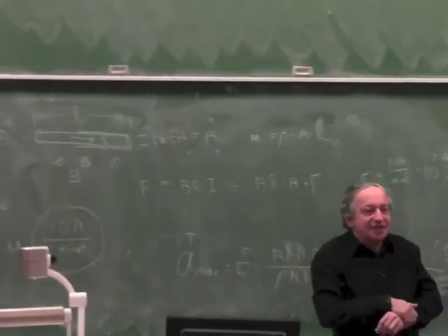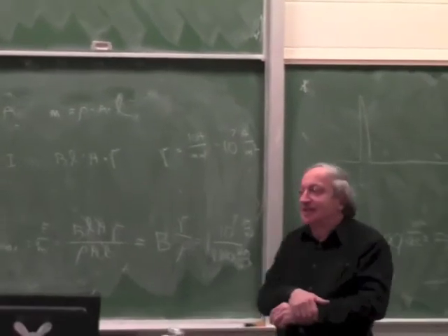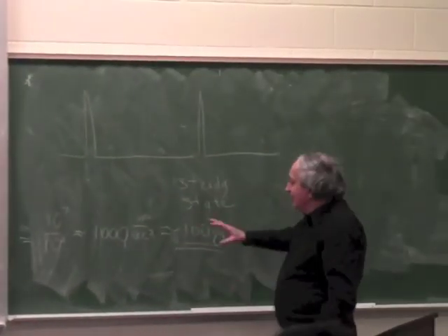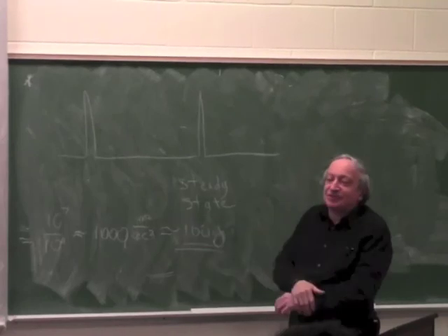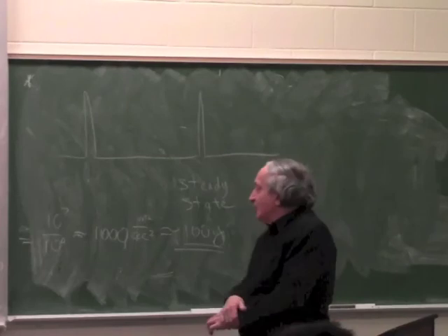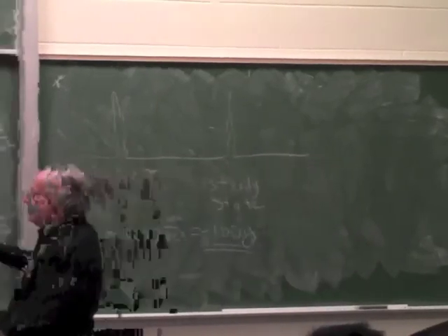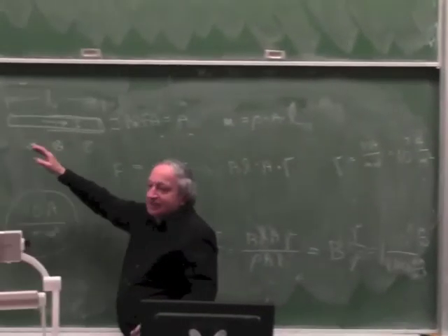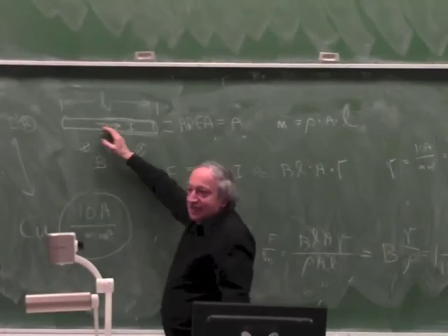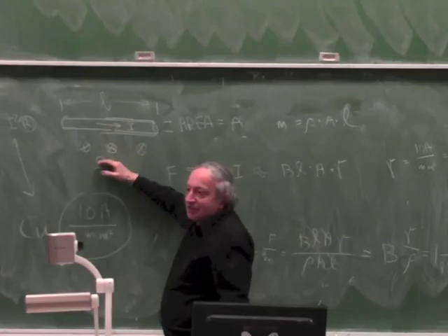But there is a very real limit which prevents us from going, say, 1,000 times this value. You can go maybe 10 times this value, but not 1,000 times this value. And that limit is demagnetization. Because when I drive that current, I started this lecture by saying the way I get a force because of the current is this current creates a magnetic field.